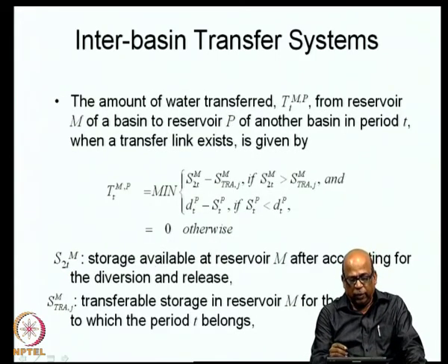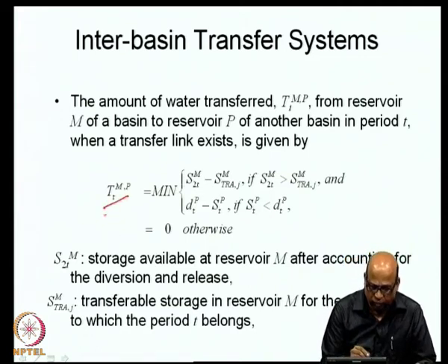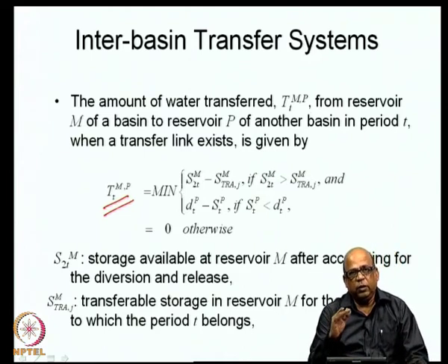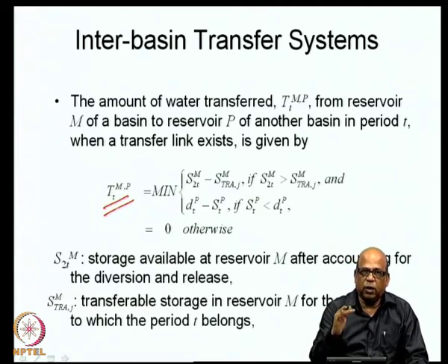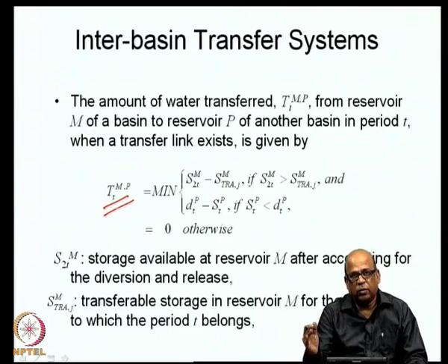Much the same way we do the transfer. So, the amount of transfer that we are looking at, by release I mean the release for the downstream reservoirs, by transfer I mean transfer for the reservoirs in the other basin. So, whenever I use the word transfer, it is from one basin to another basin. When I use the word release, it is from one reservoir to another reservoir, downstream reservoir for the same basin.